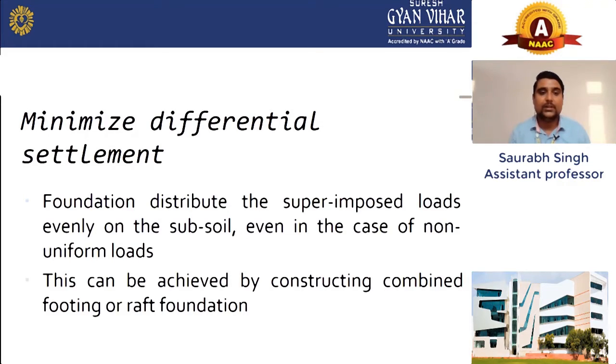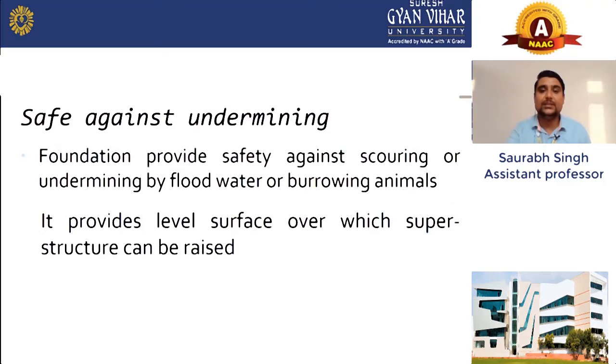Now, minimize the differential settlement. As we all know, as I told you earlier, it will also minimize the differential settlement. As given here, foundation distributes the superimposed load evenly on the subsoil, even in the case of non-uniform load. And this can be achieved by constructing a combined footing or raft foundation.